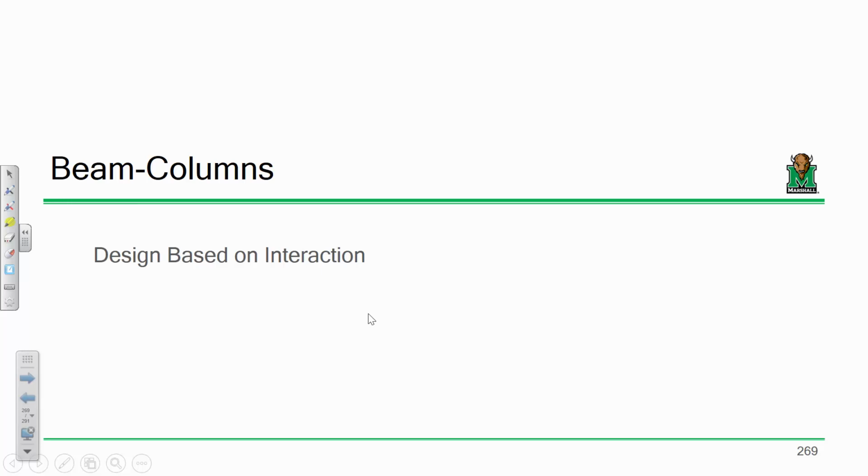Okay. Now, I would argue if I could sum up in one simple statement the one principle you need to analyze a beam, it's this. C's got to equal T, right? Compression has to equal tension. In other words, that's how we determine the moment capacity of a T-beam or a doubly reinforced beam or a singly reinforced beam or what have you. It was all hinged on C equals T, right? So I want you to keep that concept in your mind, C equals T. Now, another way of writing that, if C equals T, would you agree C minus T has got to equal 0? Okay, all right.